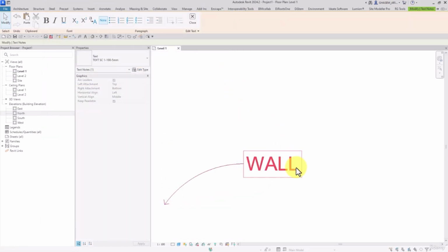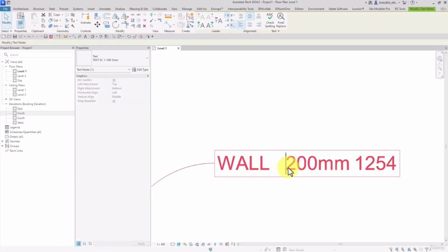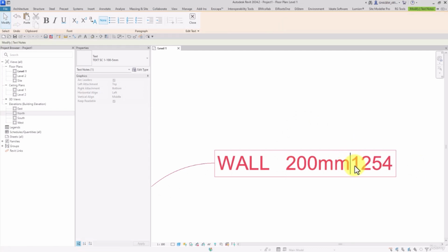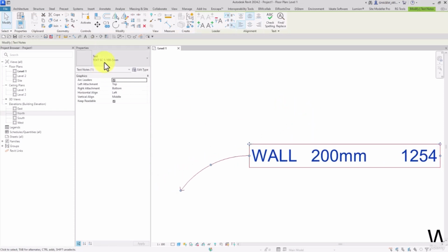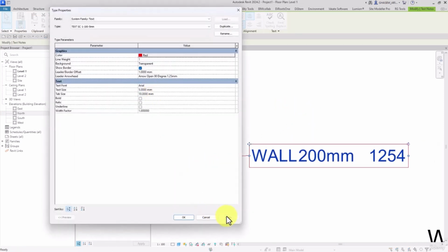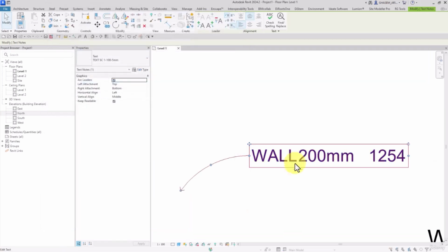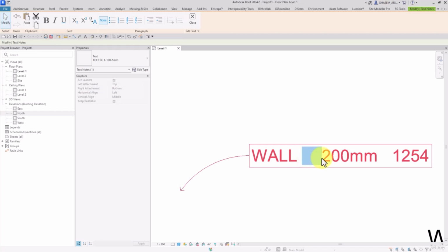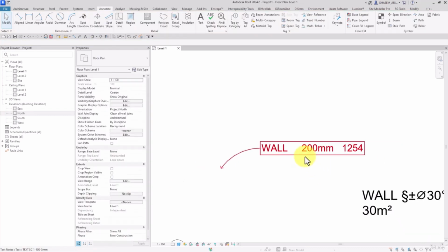I mean, if I press down Tab, as you can see, there is a 12.7 millimeters offset or space between the two. If I again press down Tab, look, this is the result. And even if I select the existing texts and then press down Tab, watch this, you can add the space of 12.7 millimeters this way. Look, this is the tab size that we can control. And watch this, in tab size 10 millimeters, or 12.7, or how much you want. And here we should add a space instead of the tab, so when the tab is removed, we get the space again.